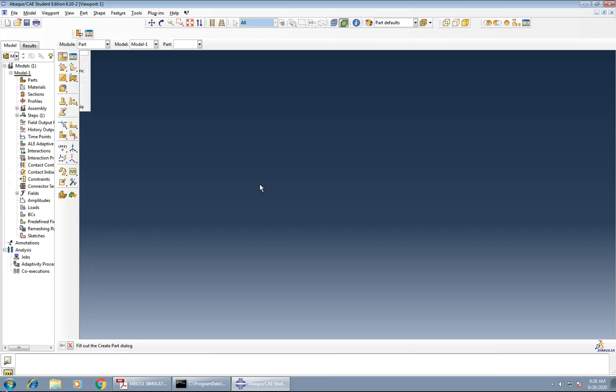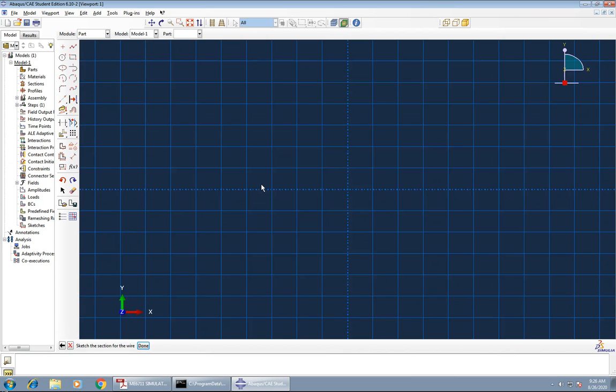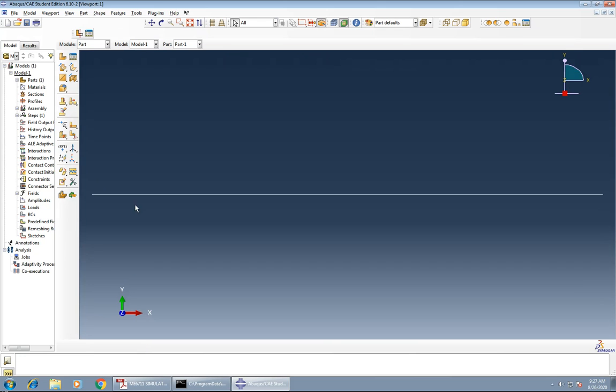So next you can see this display is going to create the wire model. So you'll be seeing the screen. Click on create lines. So click on any 2 points and then right click, escape. Right, so next you click on the dimension, you give dimension to this. So dimension is 50, enter. So you can see that line of 50 dimension is created, close and done.